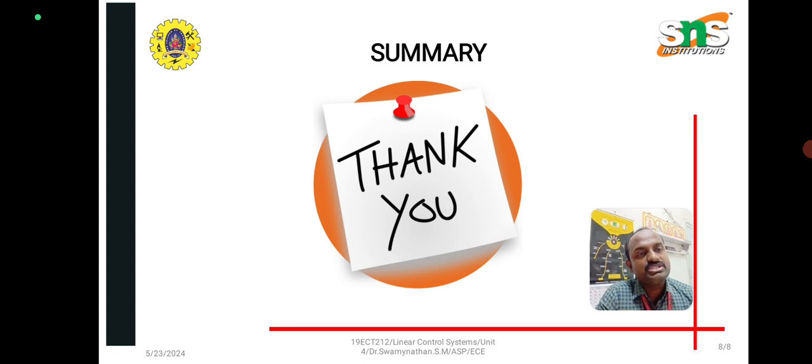First, you must know the important points of stability. If the input is controlled, the output is called stable. You can control the output based on the loop gain of the transfer function. For example, Bode plot or polar plot, everything is based on the transfer function's gain, the loop gain. Next, based on the transfer function, you can decide zeros and poles. Poles are on the denominator side, so you equate the denominator to 0 and then you get the poles.